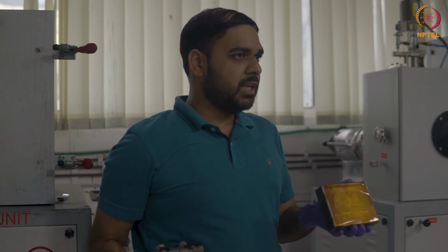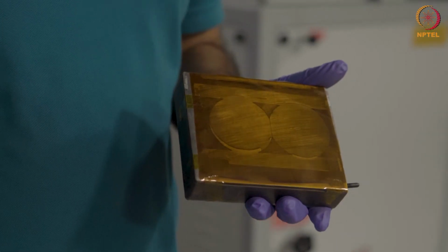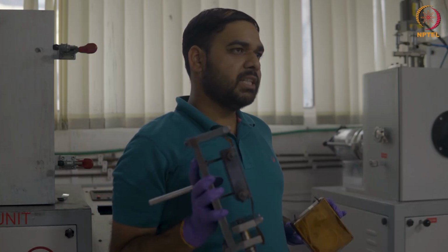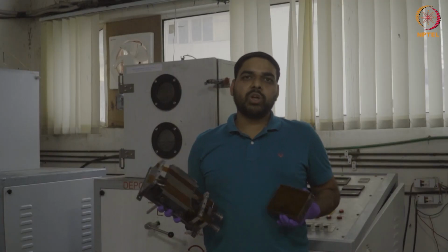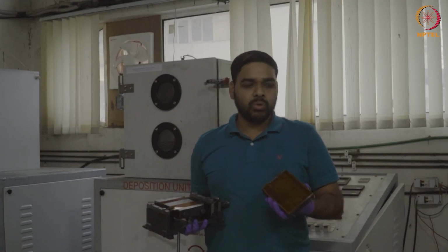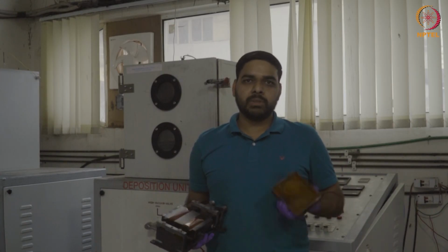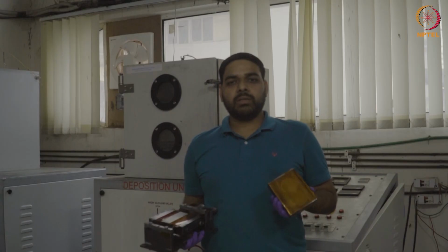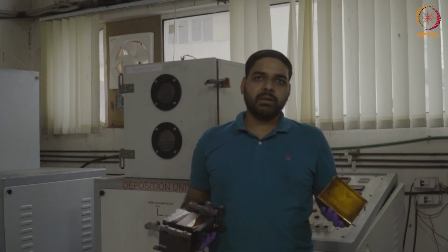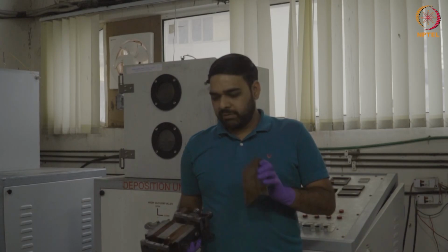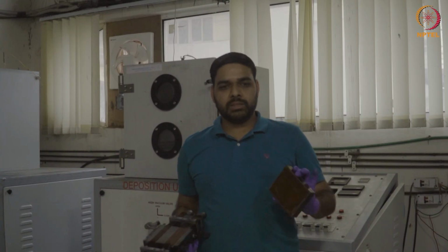We can use this Kapton polyimide in two different forms for substrate material. One is in sheet form, which you can see here in this substrate holder, and another one is in belt form. That depends on how much pre-straining we want to do in our material. This is basically for training of our shape memory alloy based thin film, because in thin film we can't do training post deposition. That is why we are doing pre-straining in the substrate itself.